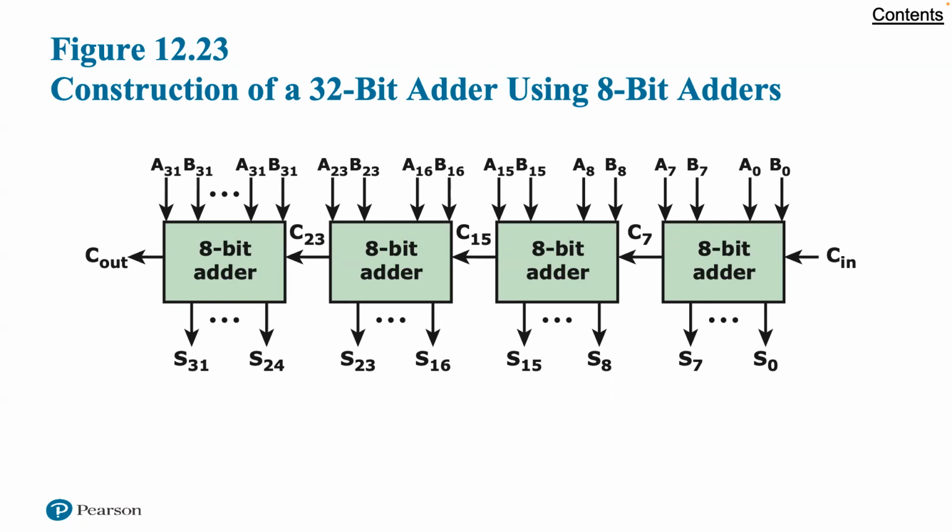Each single bit adder experiences a certain amount of gate delay, and this gate delay accumulates. For larger adders, the accumulated delay can become unacceptably high. If the carry value could be determined without having to ripple through all the previous stages, then each single bit adder could function independently and delay would not accumulate.